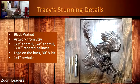Now, the background, is that finish right off the machine, or do you have to sand that to get that smooth? That's why I run the 16th inch bit at only 8% step over. Understand step over? Here's the bit and it makes a pass, and then it's going to make another pass. How far over does it go? 8% of the 16th of an inch. So that's why it's so raw, but I don't have to sand. So that is right off the machine.